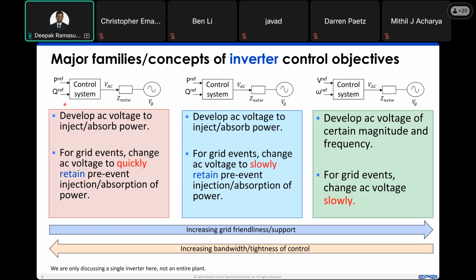On the other hand, if you have a majority of the buses as slack buses, not the theoretical ideal where only one slack bus is there, but as we learn in power flow solution techniques, there's the concept of a distributed slack bus. If you have more and more buses in that distributed slack bus set, then when you apply a contingency, the likelihood that the power flow solution converges is going to be very high.